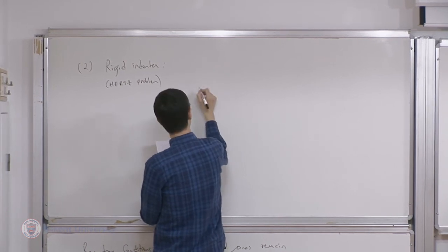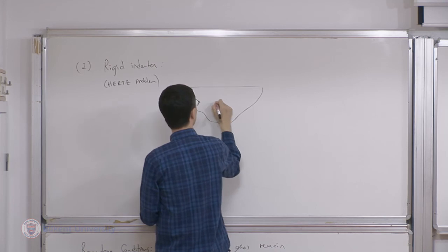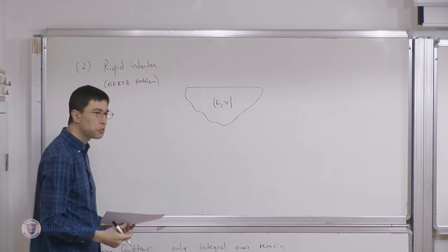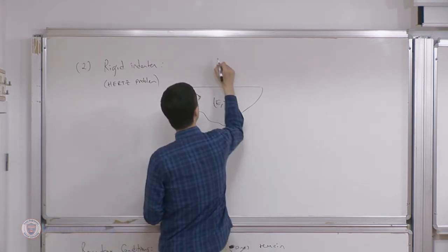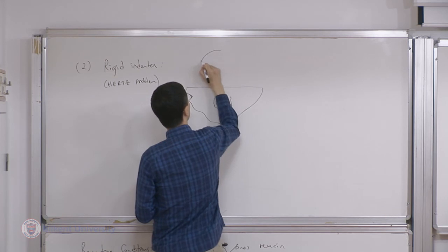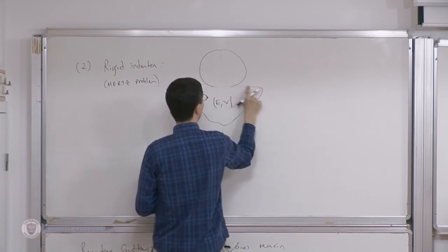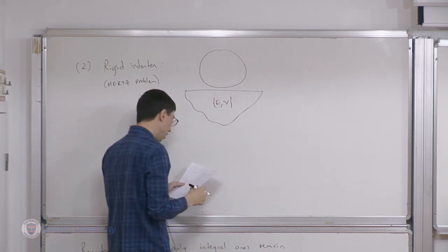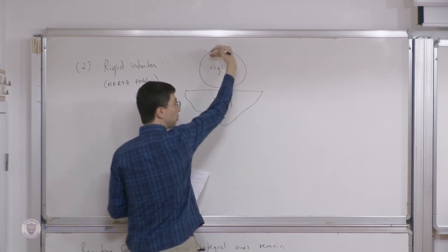The idea is again, you have a half space that we have considered, except that instead of prescribing some pressure distribution, you take a cylinder. The cylinder is rigid, and hence I called it a rigid indenter. I'm going to push it.